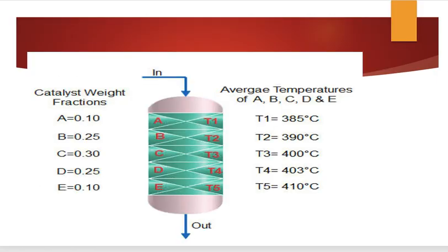Here in this reactor, we remark that there is a difference between the volume and weight of part A and part C and part B. Is it clear for all that part C weight and the volume is more than part A? And for sure the effect of the temperature difference for this part of the layer A and B will be different, so you cannot make direct summation when you calculate the weight average bed temperature.